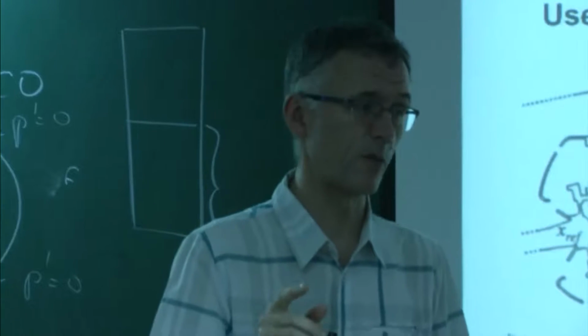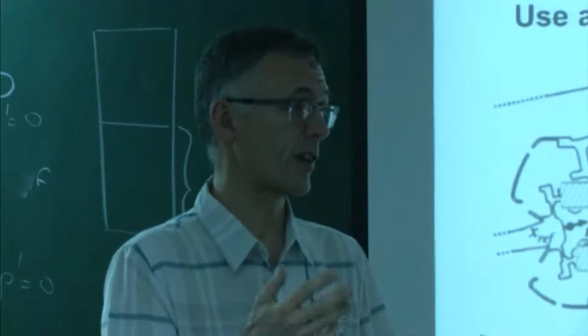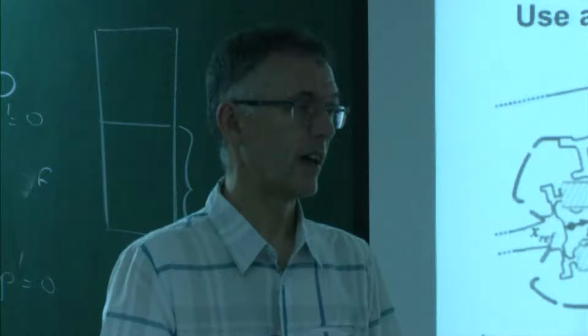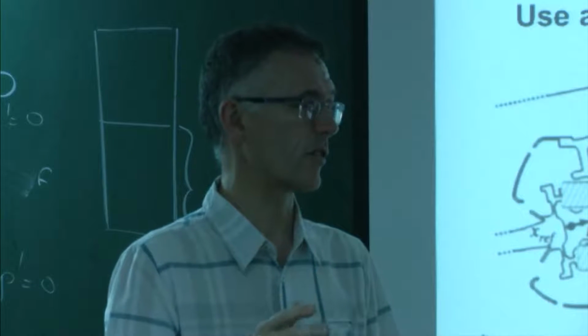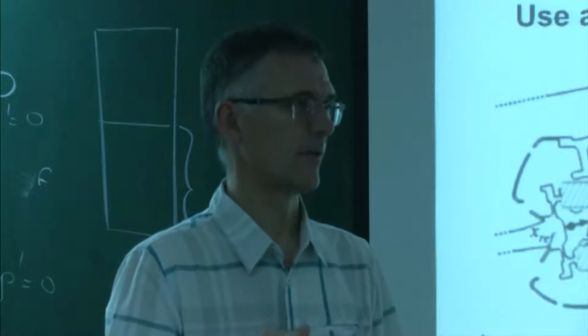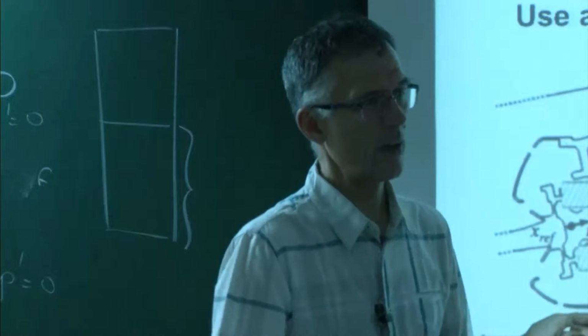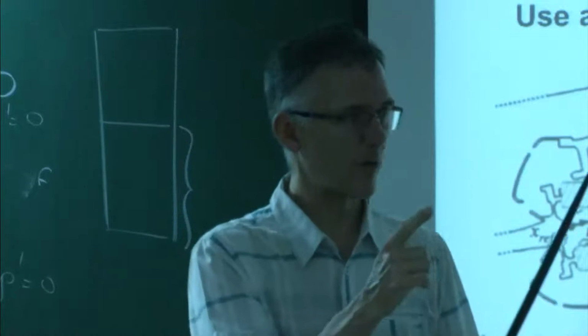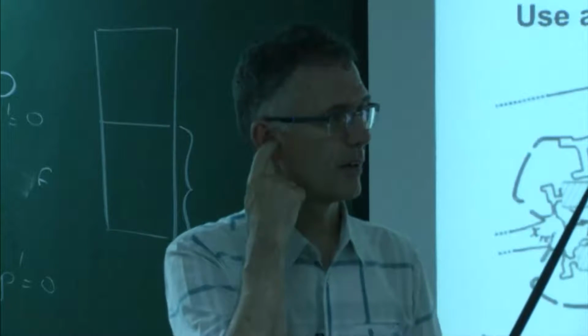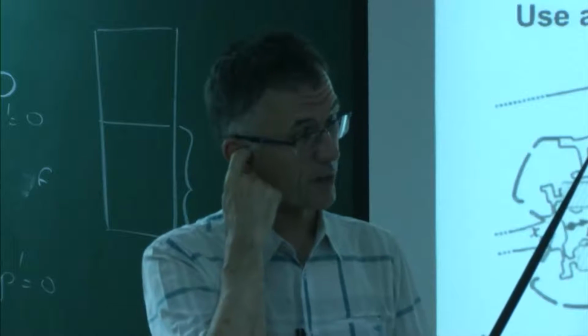If you don't do it at 0 Mach number, you're basically talking about the linearized Navier-Stokes equations. And we know that solving the linearized Navier-Stokes equations is difficult. This is why we usually stick to saying that the Mach number is 0 in the chamber, because it's much simpler. Instead of 5 equations, you have to solve only 1. So if you want to do that, you can, but it's going to be difficult.